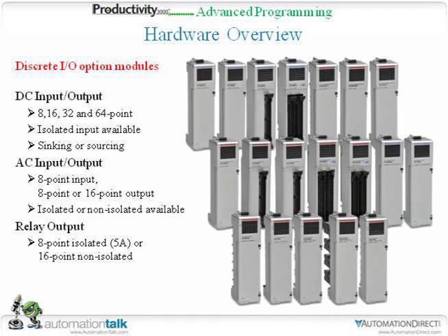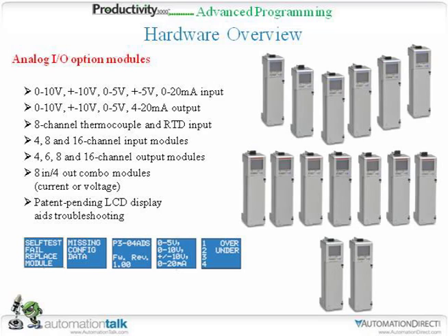Next slide. There are 35 different I/O modules, all in AC, DC, input, output, and relay output, of course. On the next slide, part of those 35 modules include analog inputs and outputs, both in voltage and current. In our demonstration today we're using quite a wide range of the analog modules. Actually, I don't think we're using any discrete, because all the high-powered instructions involve numeric type values and information. Discrete is discrete.